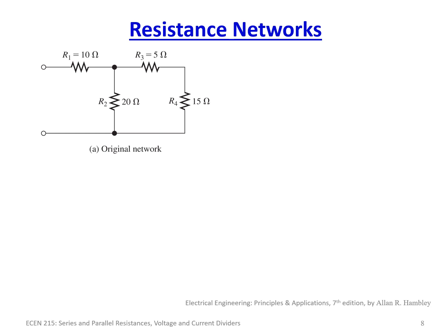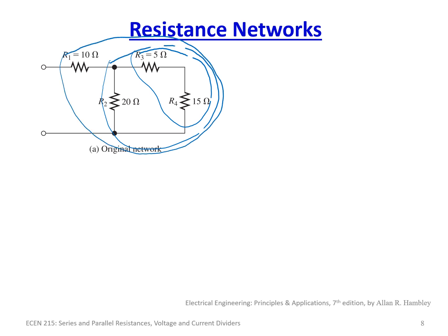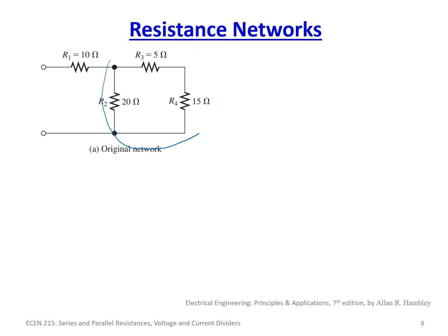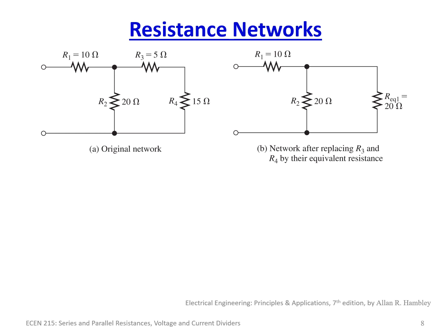First, we note we have these two resistors that are in series, right? And then this whole chain right here on top of that is in parallel. And then that will be in series with that. So there's kind of 3 parts to this problem, if you will. So let's take it one by one. Let's first start with the 5 and the 15 ohm. Since they're in series, we add them together and we end up with this circuit.